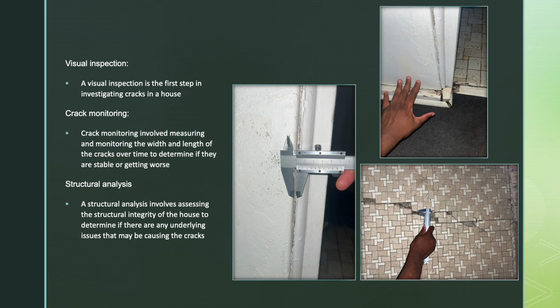Structural analysis involved assessing the structural integrity of the house to determine if there are any underlying issues that may be causing the cracks. This technique involved examining the foundation, load-bearing walls, and other structural elements of the house, as this technique helped determine the cause of the defects.